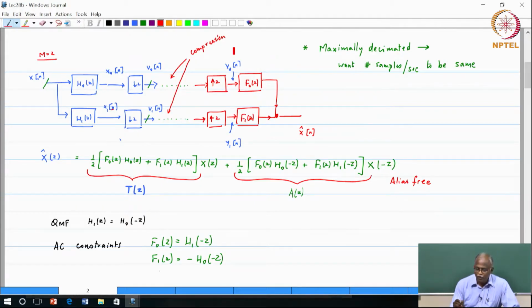So the input output relationship, we will not revisit it, basically can be written in terms of the input signal and the alias signal. The constraints that we have used in the past, this is for alias cancellation, this always guarantees that aliasing is cancelled. We also wanted to force a relationship between H1 and H0, and one of the ways in which we said was this was option 1. And this brought us to a point where we could make some trade-offs between phase and magnitude errors, but we could not eliminate both of those.